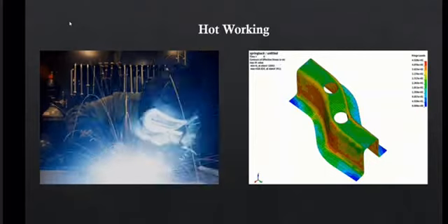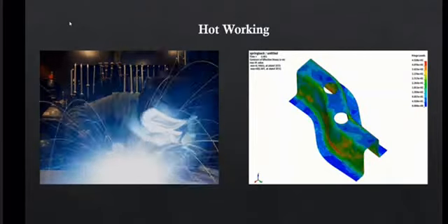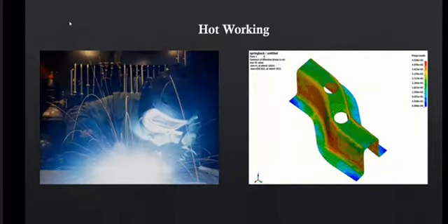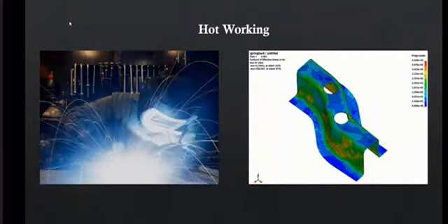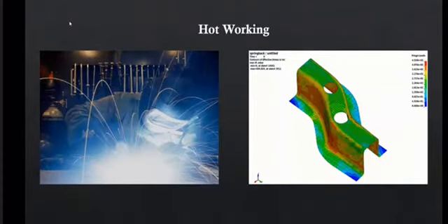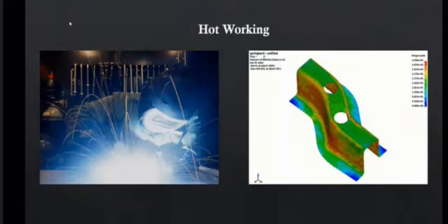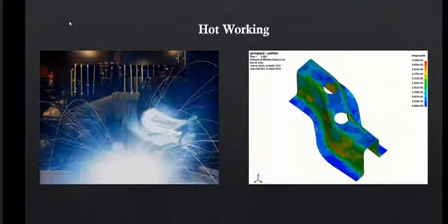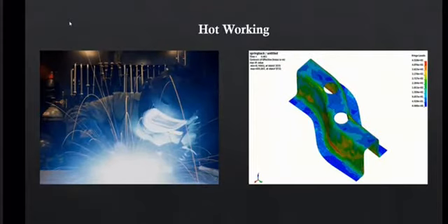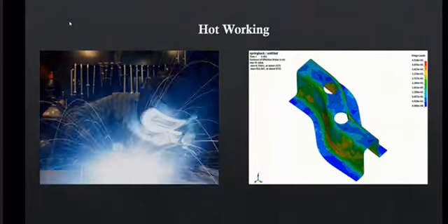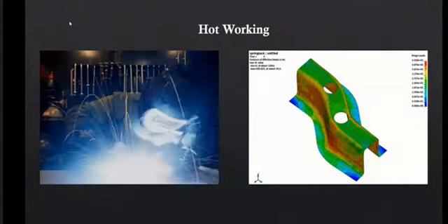The dividing line between cold working and warm working is often expressed in terms of the melting point of the metal. The dividing line is usually taken to be 0.3 Tm, where Tm is the melting point or absolute temperature for the particular metal. The lower strength and strain hardening as well as higher ductility of the metal at the intermediate temperatures provide warm working with the following advantages over cold working.